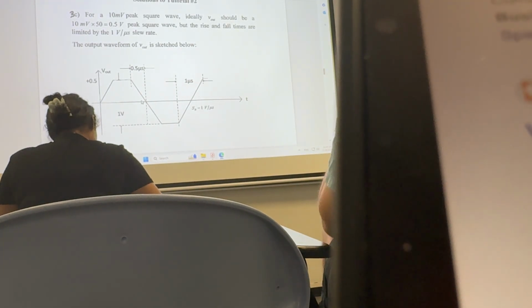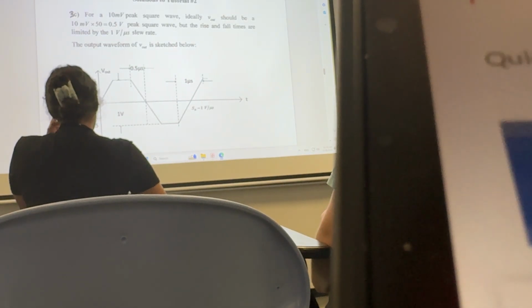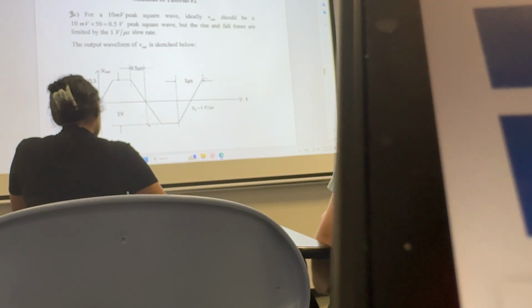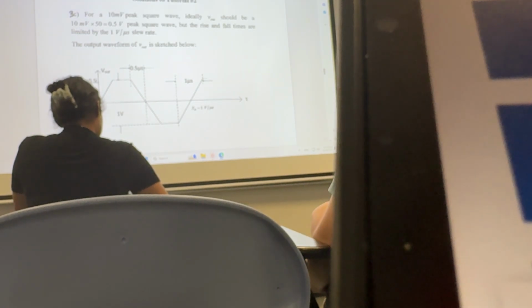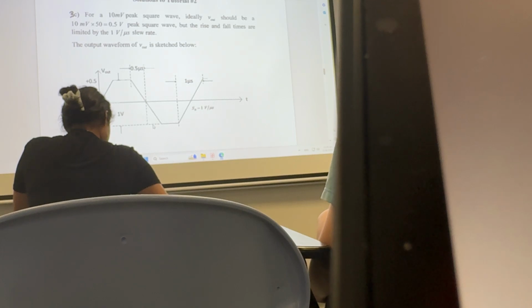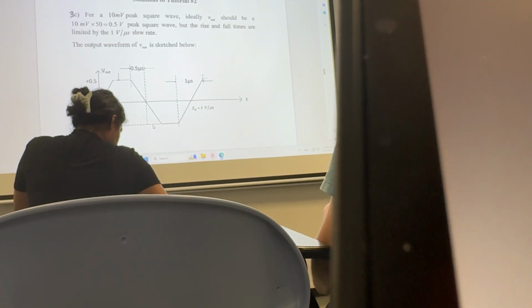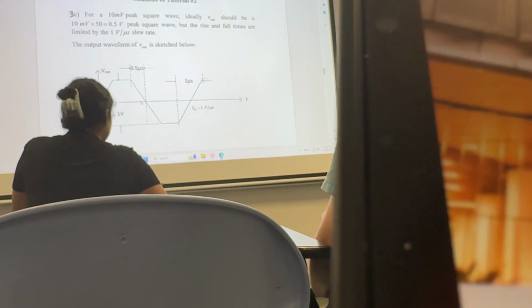So this is a response. And the output, right? So the square perfectly goes up, perfectly goes down, but definitely will exceed your slew rate. Because the slew rate has a number, right? You go straight up, straight down, that needs an infinite slew rate, right? Only an ideal op amp can do that. But all op amps are not ideal, right? They have a finite slew rate. So all op amps responding to the square wave give a trapezoidal wave output. So that's why you can see a trapezoidal wave output.